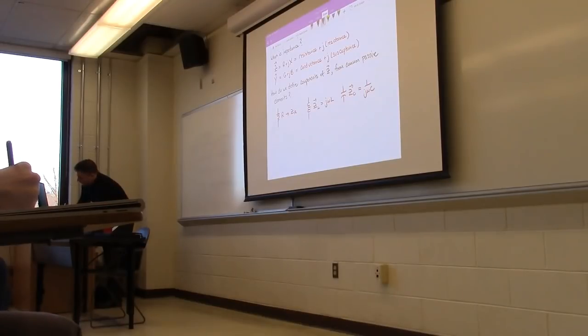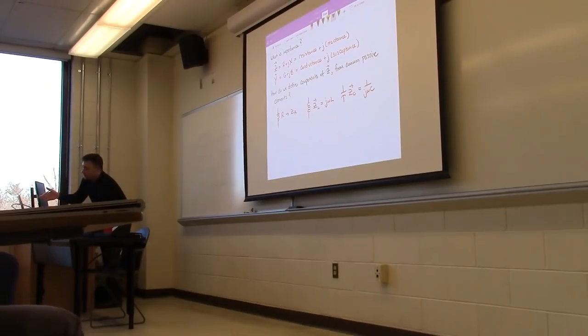If you want to calculate the impedance in a polar form, I don't think this equation is really worth writing. Essentially, it's the same thing, Pythagorean theorem and inverse tangent. I have a version of the equation where it puts it in terms of R, L, and C, but really that's not a very useful formula because it would depend on what the circuit is.